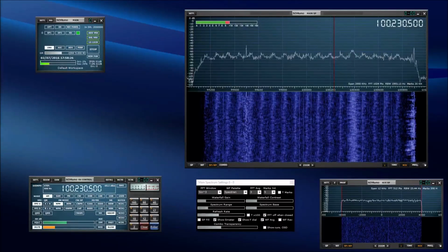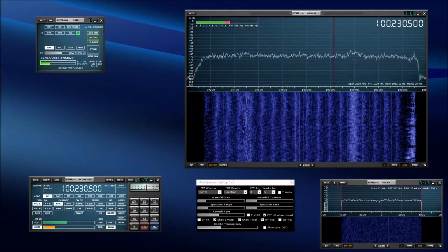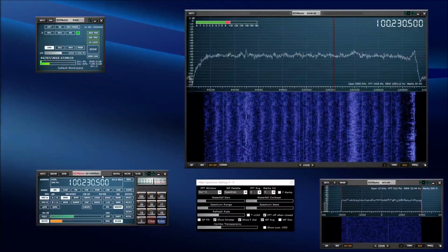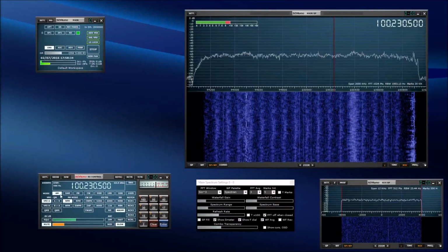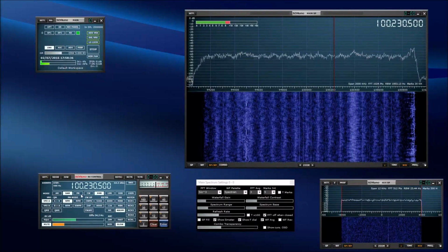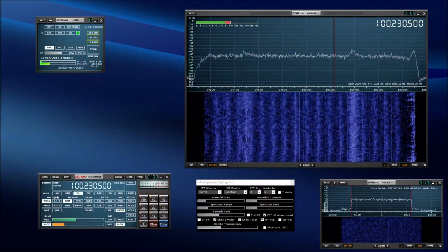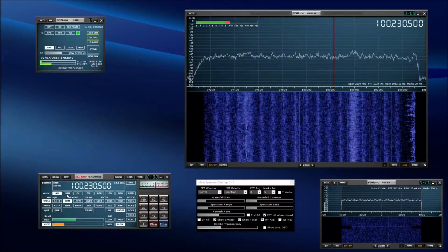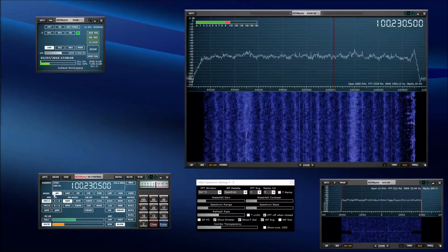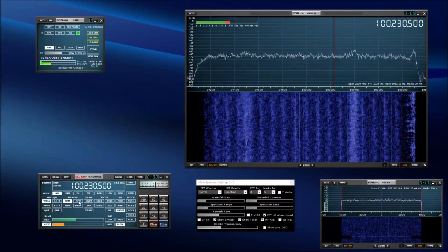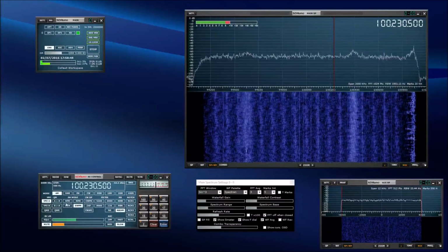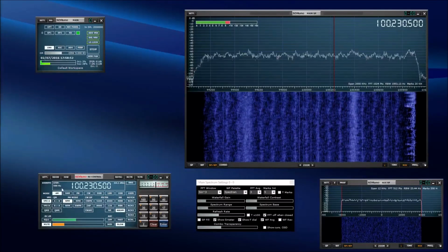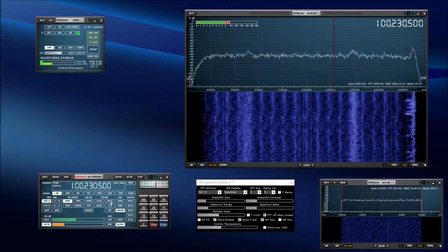Yeah. Some people have said to us that there are some slightly odd things with the filter bandwidths. In the receiver control window, if you select some functions, they stay lit. Some functions actually stay lit when they're not in use. For example, I'm in AM mode, but I can still select all of the FM modes, and that's slightly confusing people. And also some of the filters.